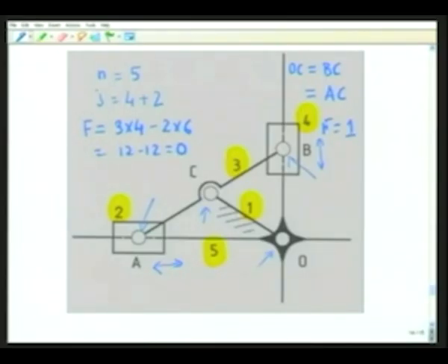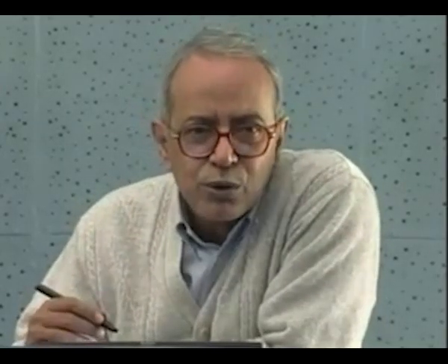In fact, as we will see, the angular velocity of link 3 to that of link 5, which are both rotating with respect to fixed link 1, will be exactly half for these special dimensions. This is known as the cross-slider trammel, and I would like to encourage the students to show why it moves, by starting from the elliptic trammel that we have discussed in an earlier lecture.